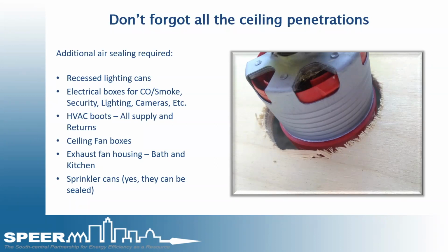There's a ton of opinions out there, whether to seal, whether not to seal. The escutcheons, which you see here, this gray metal escutcheon, can be sealed to the drywall opening without compromising the safety or proper operation of the sprinklers. But most of the time that still requires the fire marshal or manufacturer to sign off, so there's usually pushback on that. According to the National Fire Sprinkler Association back in 2020, they basically said the same thing. This can be done, but needs to follow manufacturer specifications.